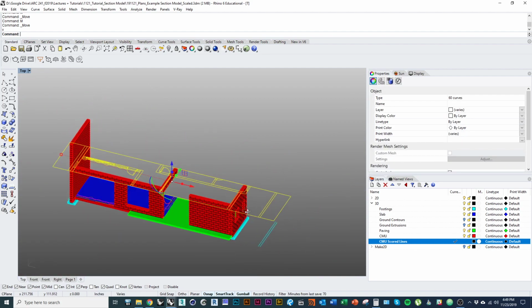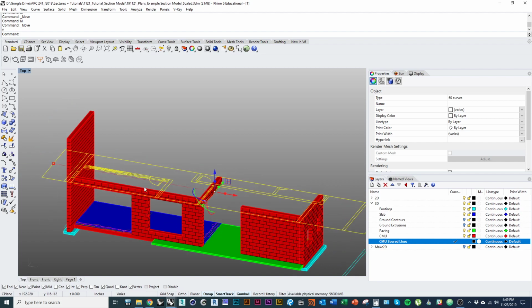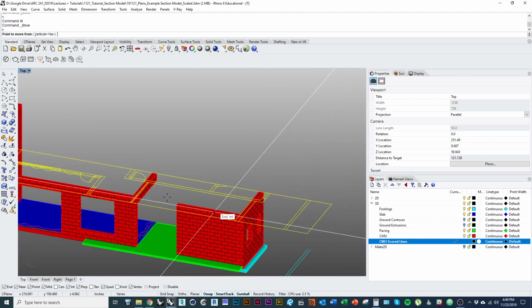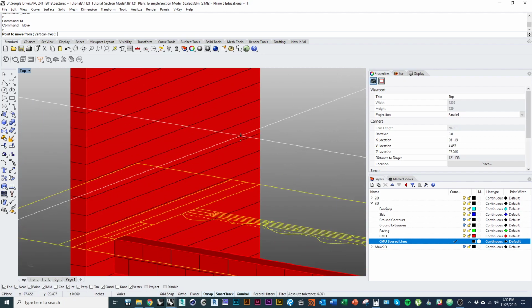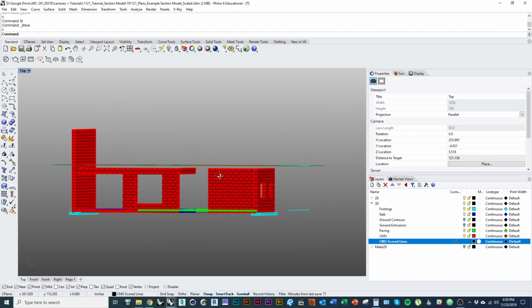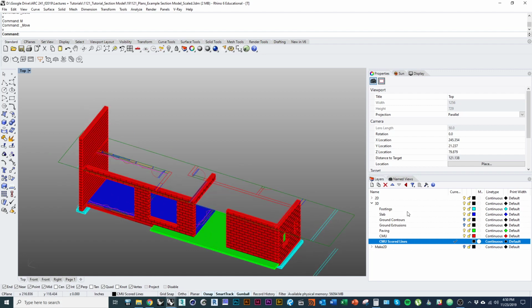And I'm going to go right up to where the top of those walls are on my first floor. And then I'm going to move it one more course up. And what I'm leaving there is the space for our floor framing, which is the other half of what we're going to cover in this video.